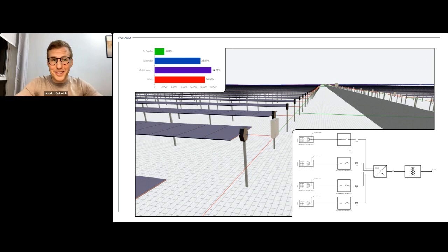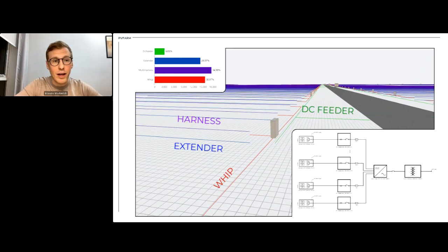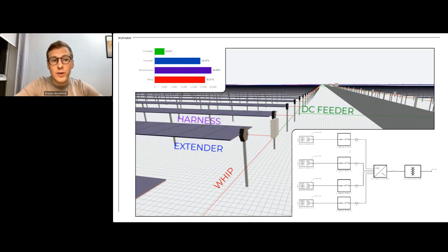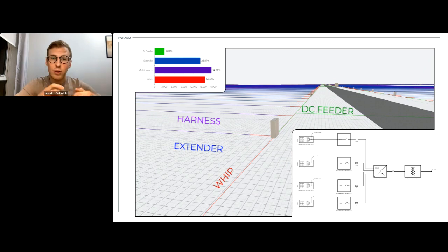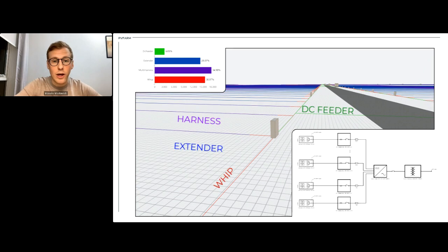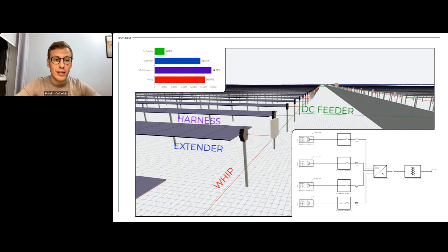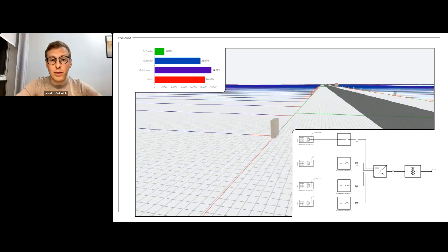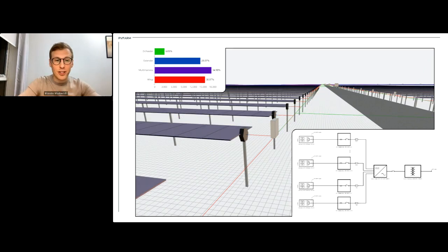And quite obviously, there is another important aspect, which is electrical considerations. The electrical considerations dictate a skid position, because you want your blocks to be as compact as possible to ensure efficiency and cost optimization. Sometimes the skid position and the electrical connection can define whether you're going to use trackers from that particular area or not.